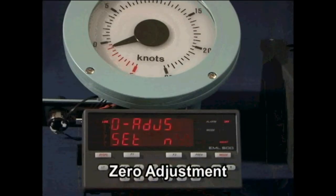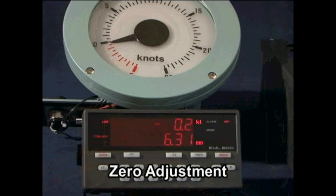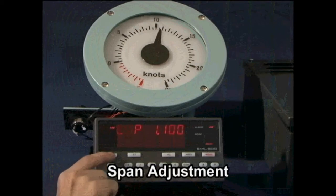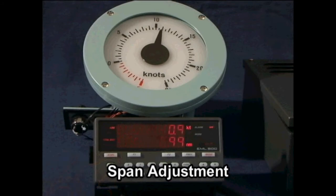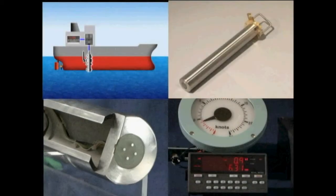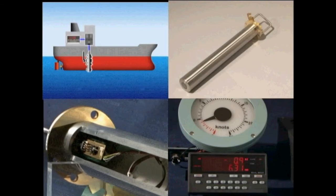0-point adjustment is conducted when the 0 point of the sensor itself has changed, such as when the sensor is replaced. This adjustment is made when the ship's speed is 0, that is, at anchor. Span adjustment is necessary when log speed is misreported due to fouling of the hull and so on. Sensitivity adjustment is necessary when the measured value changes due to difference in sensor sensitivity, such as when the sensor has been replaced. Remember to read operating manuals before making these adjustments.